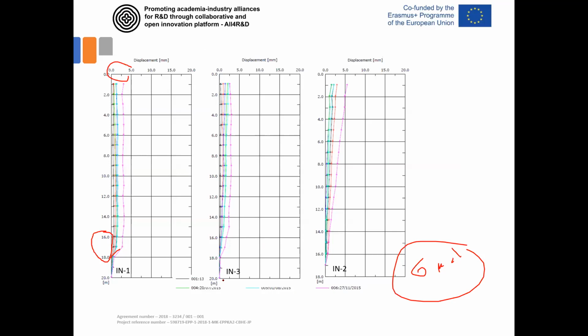This line began to increase its displacement, and the results look like 10 or 15 millimeters, indicating that the displacement is very, very slow. So this is a so-called creep slide more than a landslide, where you have about 5 centimeters per year. So very slow creeping is observed here, and that's why it still works to just change the pavement after 1 or 2 years when small cracks are found at the surface. And so far, actually, nothing has been performed here as a remediation measure.